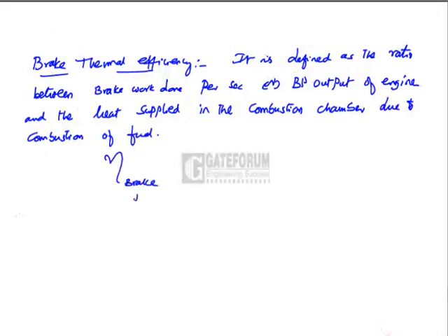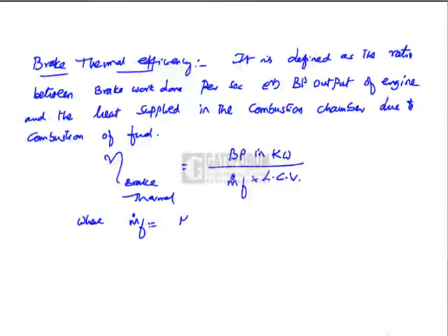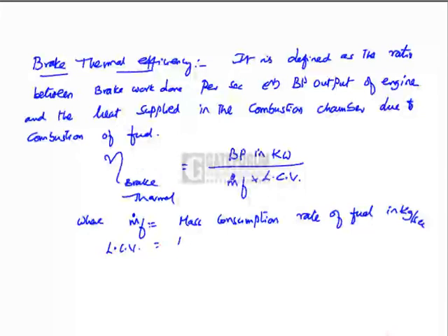Brake thermal efficiency is brake power output in kilowatts divided by m dot f into LCV, where m dot f is mass consumption rate of fuel in kg per second, and LCV is lower calorific value of fuel in kilojoule per kg.